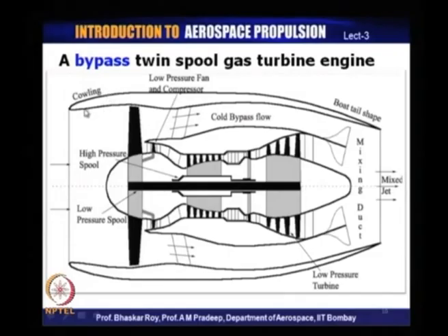In a high speed aircraft, the design of this cowling is a very important issue, and it appears in the design right in the beginning, and it is a very long drawn out affair. The entire outer surface of the engine needs to be appropriately designed. As you remember, in many of these aircraft that you may have seen, the engine is hanging outside the aircraft, quite often hanging from the wings, and this entire outer surface is open to the air that is flowing.